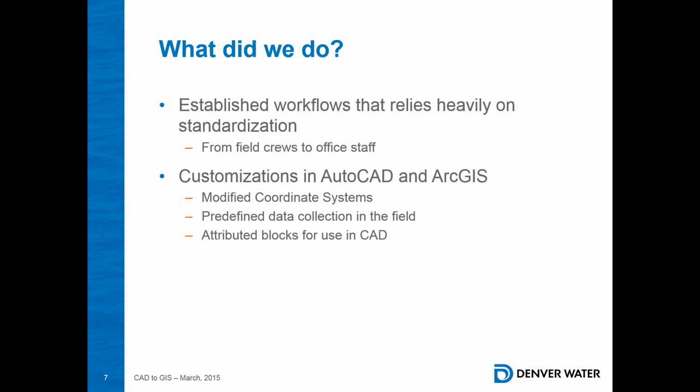they collected that out in the field or in the original attribute, and we bring it into CAD as a CAD point. Or we can drag and drop as a shapefile if we wanted to just reference the data. But we've designed it to where we can actually import the points, and it automatically populates these attributed blocks. So now we've got the exact same information that they pulled from the field in our CAD drawings that we use to send to our asset recording group.